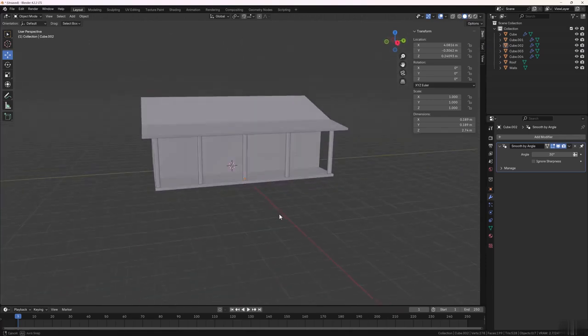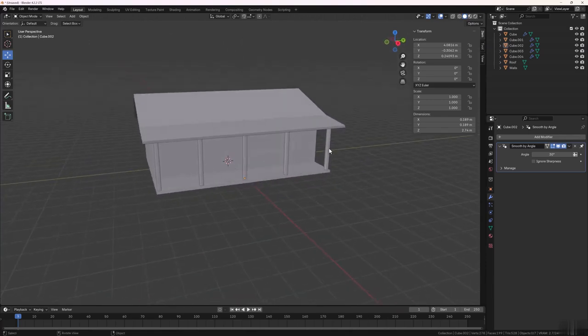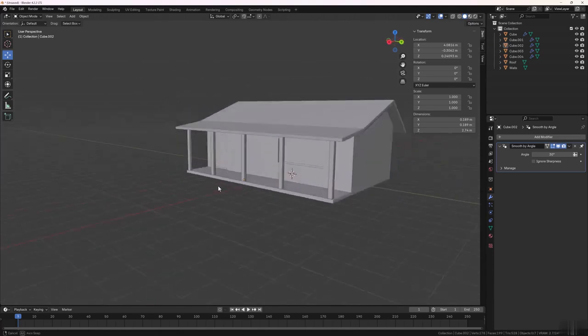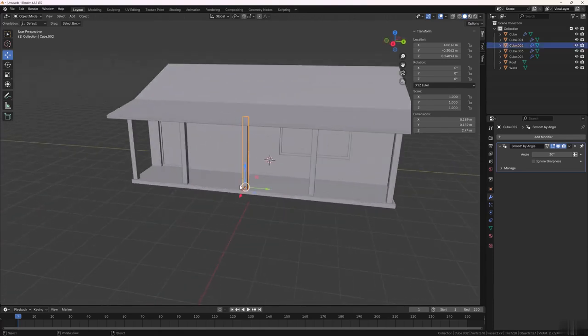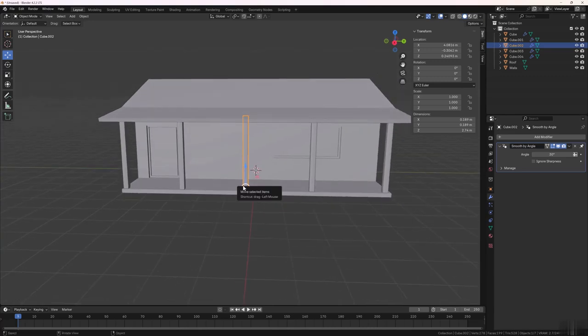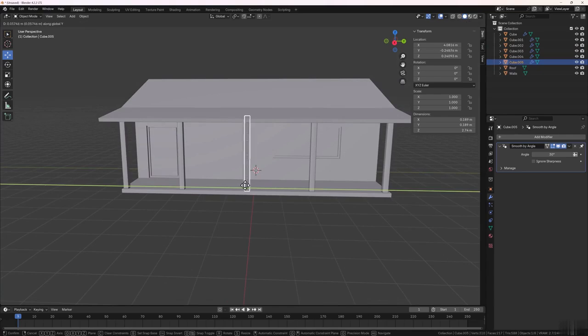So we could now, if we wanted to, maybe just put a horizontal rail in there. That's one last little thing to do. So let's grab this one here. And let's press Shift D. And we'll press Y. And we'll pull that one out into the middle.